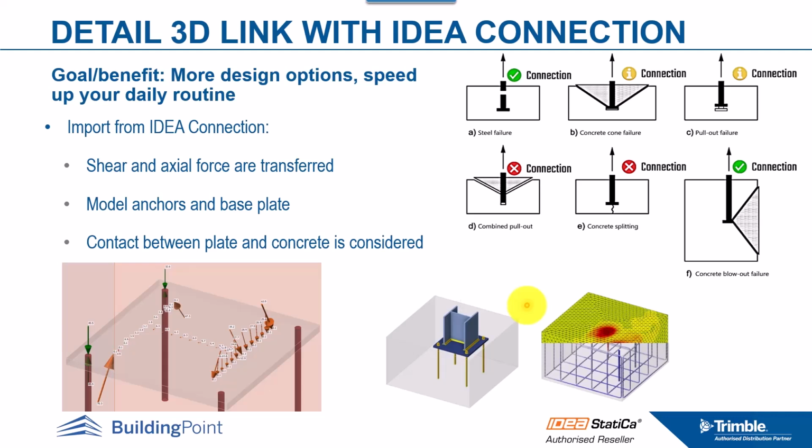But in terms of base plate design, you actually have some difficulties in IDEA StatiCa Connection. That's why we introduced the Detail 3D application, just to get rid of those limitations that we have in IDEA StatiCa Connection. And not only that, in Detail 3D you can add the reinforcement and you can check the anchor's capacity, considering the effect of reinforcement as well.